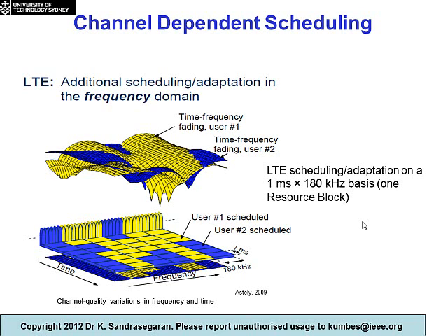How do channel measurements look for user 1? Okay, so remember, channel measurements have two aspects to it. There's a frequency aspect, because you're making channel measurements across different resource blocks, and there's also a time aspect, because you're making channel measurements every TTI. So you can see on certain resource blocks the yellow is better, and on certain resource blocks the blue is better.